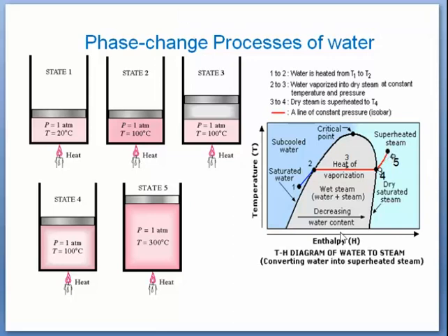And one more thing you can observe, that as we are moving ahead, the enthalpy or the total energy of the substance is also increasing, or rather you can say the total heat content of the superheated steam will be more in comparison with the dry saturated steam, and its work developing capacity will also be quite high in comparison with the dry saturated steam.